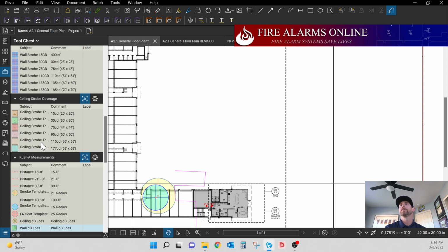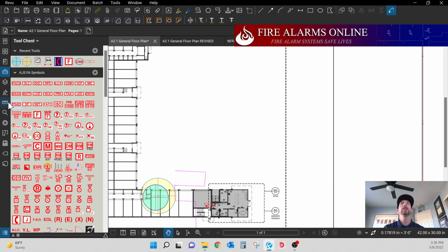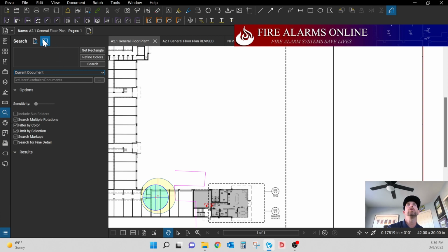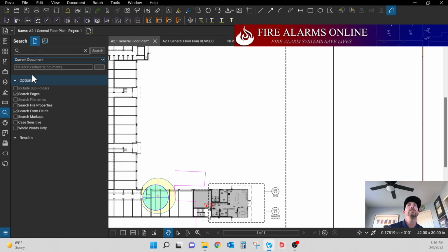Let's see, as we go down over here, so we're on measurements. So search. Bluebeam has a great search tool. There's 2 items I use in it. You can either search by text, just like any other typical program you've ever worked in, like Microsoft Word or Excel. Control F will open up the search menu. You can type your text into here and select search, and all your results will pop up down here by page. You can click directly on them and it'll bring them to a highlighted area within the document here.